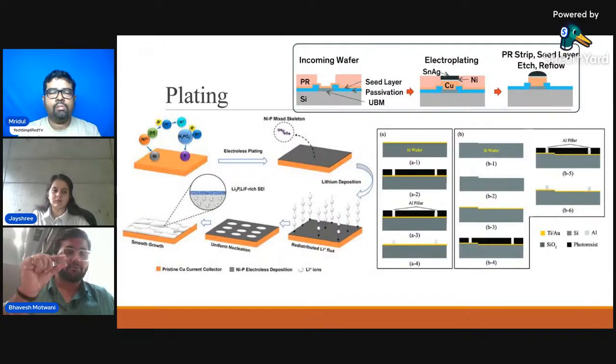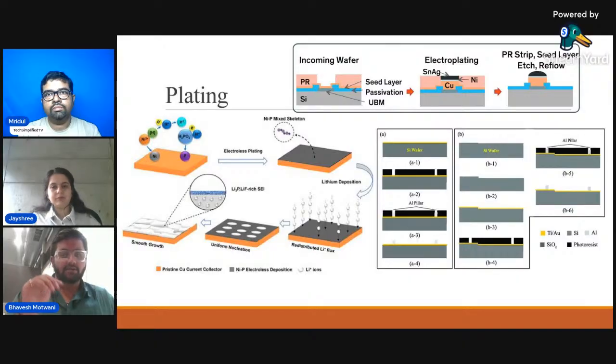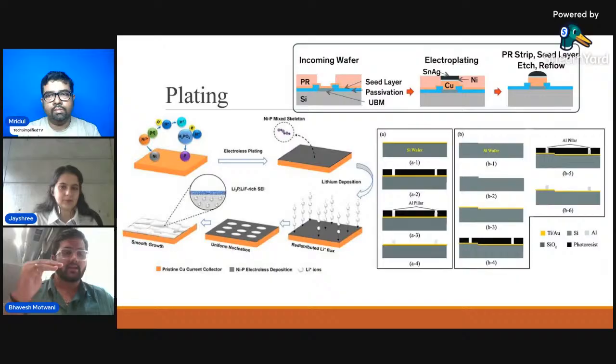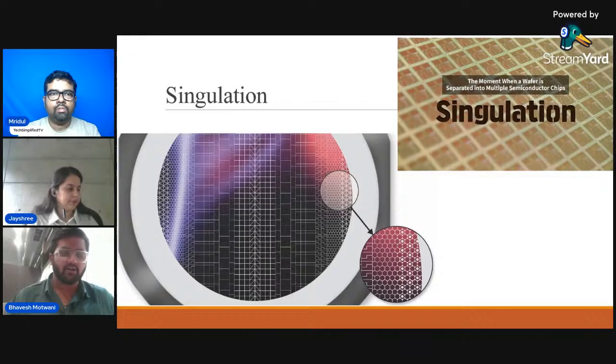So we have a proper metallization part, which can be helpful in a BGA, ball grid array, wire bonding, to make a proper under bump for better metallization specifically. And the third image is the same, doing the metallization of different dies to make a stacking of them, and then for better electrical conductivity and thermal conductivity also.